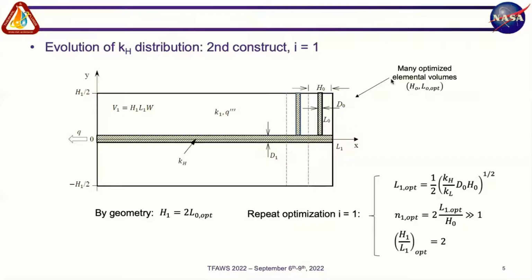And what I do now is, if I place my first construct perpendicular to this strip, I essentially start building a very complex, geometrically complex structure. That's what we call a tree network, to cover the entire volume, and by doing so aim at reducing your maximum temperature or facilitate the heat flow from the volume to the point. And that's what I mentioned beforehand. This structure that we are building here, that we are seeing evolve in time, looks like structures that we see in nature: the lung, the tree, the river delta.